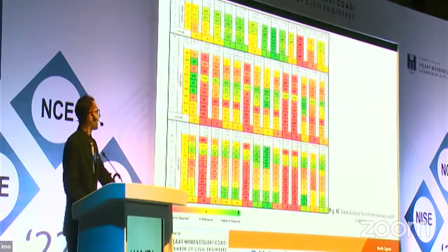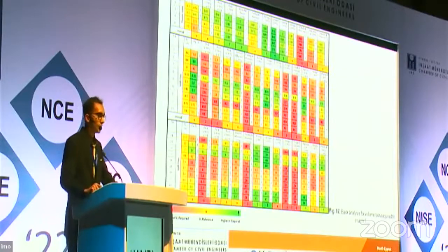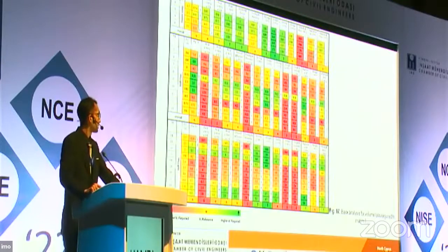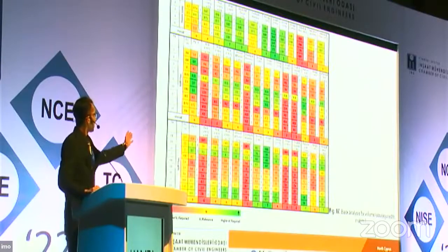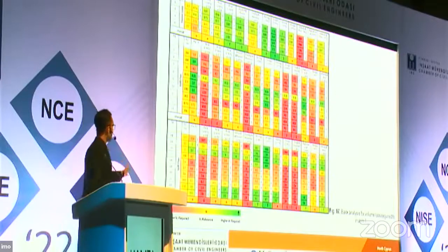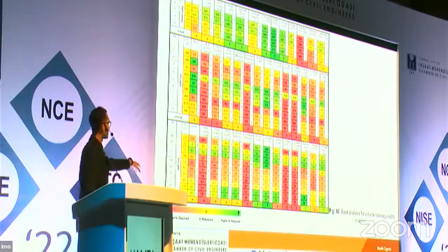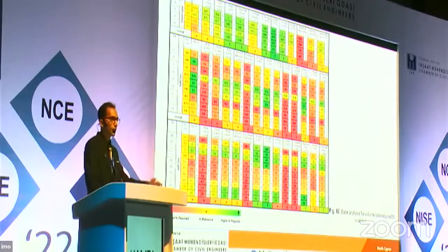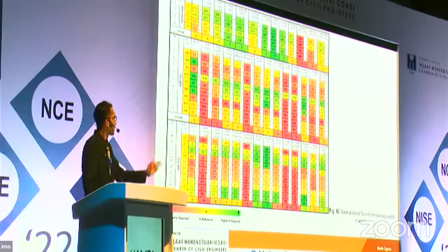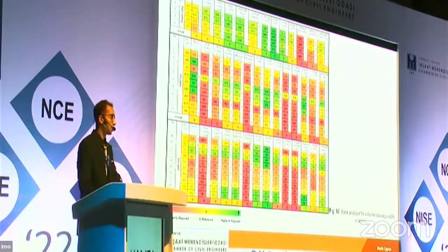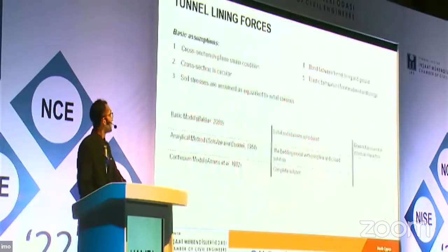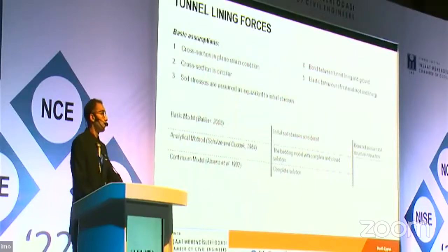So this table is the back analysis chart for volume loss. It can be quite helpful for practicing engineers as initial guidance. On the extreme left hand side, we have our equation, and for the back analysis, our overall performance shows that the VL reference, which can be calculated beforehand, can be quite similar. Whereas if anyone prefers other equations, it can be a guidance that either higher volume losses or lower volume losses should be considered. So then, of course, we have to design our tunnel.